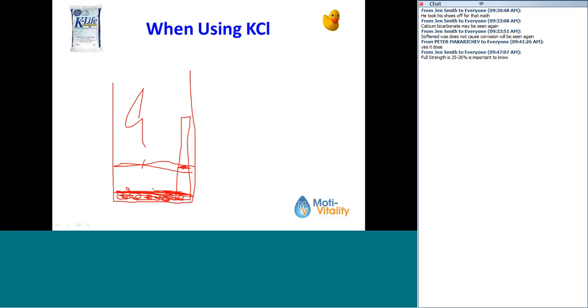So even though the salt's dropping down there, you've got less water here because the float's still shutting it off here. So the solution here is, a lot of times they'll put a grid plate down, which keeps the salt level up higher than what might drop down here, and that helps a little bit.